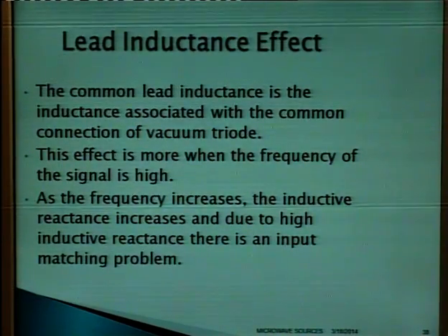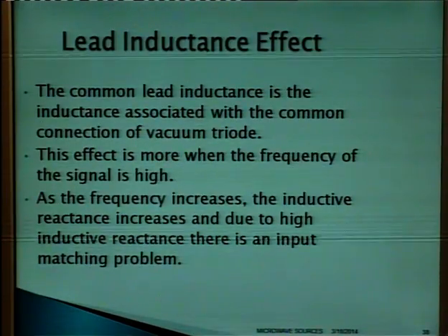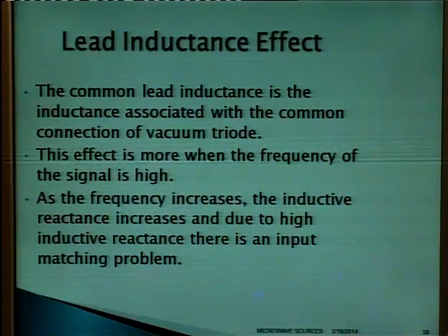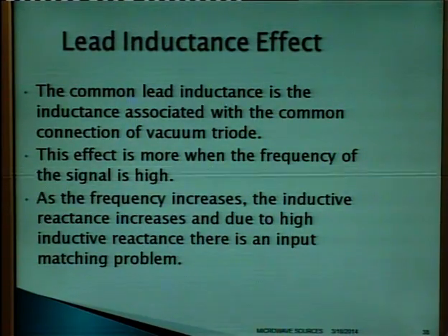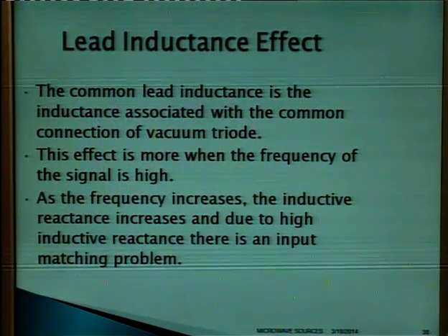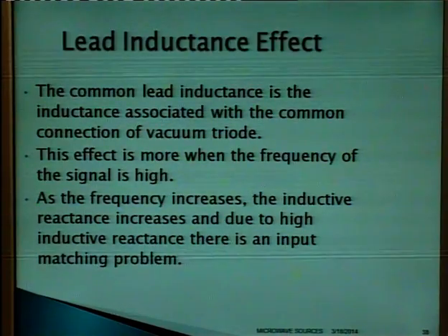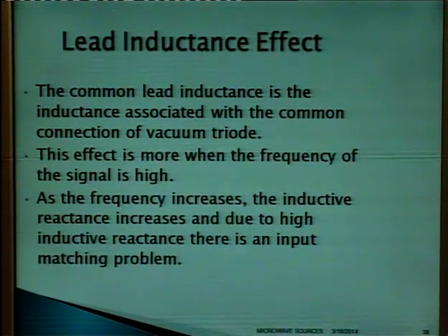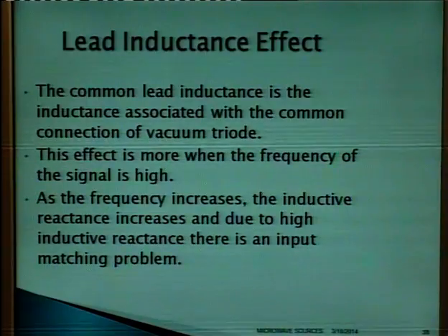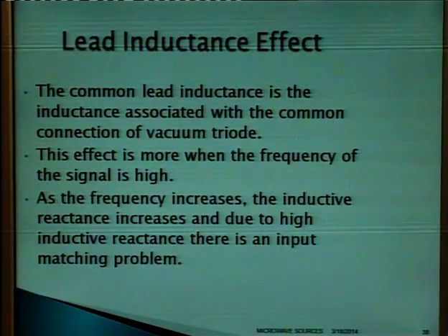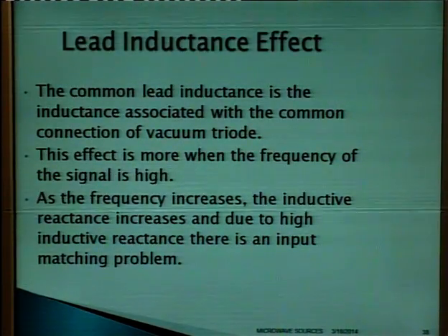Then we have the lead inductance effect. The common lead inductance is the inductance associated with the common connection of a vacuum triode. This effect is more pronounced when the frequency of the signal is very high, meaning it comes into the picture when the device is operating at very high frequency. As the frequency increases, the inductive reactance in the circuit increases, and due to high inductive reactance there is an input matching problem.